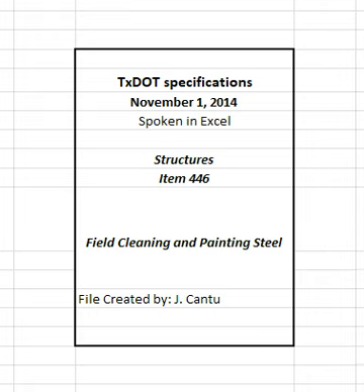2.1.1 System 1A, Overcoating, 1 coat. Provide an overcoating System 1 in accordance with DMS 8105, paint, 1 coat overcoat, and the manufacturer's specifications. 2.1.2 System 1B, Overcoating, High Corrosion Environment. Provide paint in accordance with DMS 8101, Structural Steel Paints Performance. Provide a penetrating sealer, intermediate prime coat on bare steel areas, and an appearance coat in accordance with manufacturer's specifications.